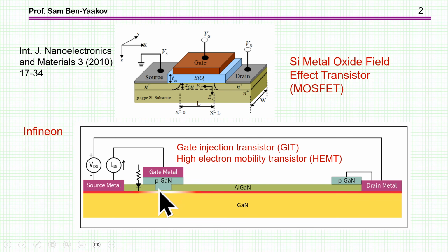There is no insulation here. In fact, it looks like a diode between the gate and the channel, the source, you might say, in this case, and it is therefore conducting DC. It can conduct and should conduct, in fact, for proper operation. So the driver has to be designed such that it will take care of this DC component. And this is the subject matter of this presentation.